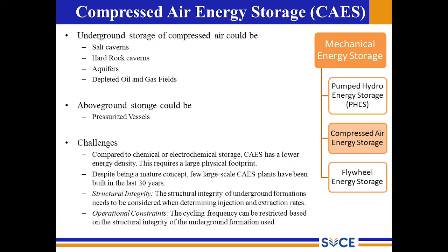structural integrity. When you're going to be storing this compressed air in your underground caverns, the integrity of your below ground installations plays a major role. Since you're going to be dealing with high pressures up to 200 bar pressure, it is very important that your storage is safe to operate.